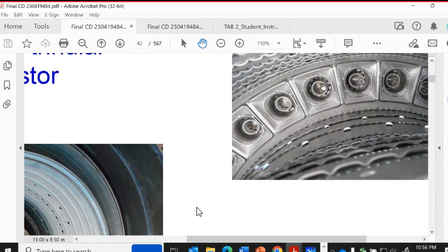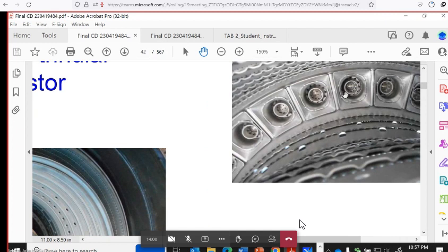Or it may cause a lower temperature flame to be produced because I've got some of the nozzle portion blocked through here, and I'm not getting as strong of a flame pattern as I might be coming out of the other ones. But like I said, we're in such close proximity with all these, I'm able to maintain stability across. So it gives us a lot longer life on the combustor, a lot better heat dissipation. We get about 30,000+ hours of operation with a combustor section before you have to worry about doing a hot section change out.